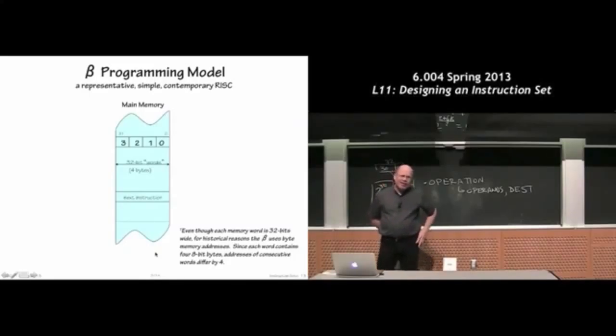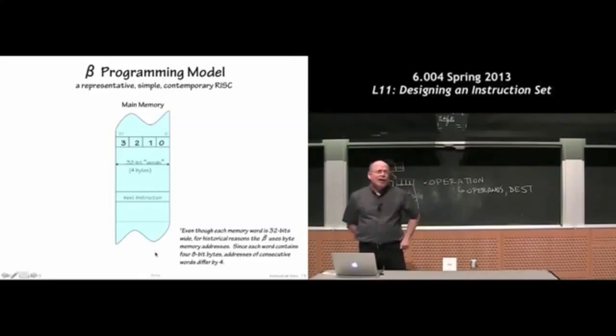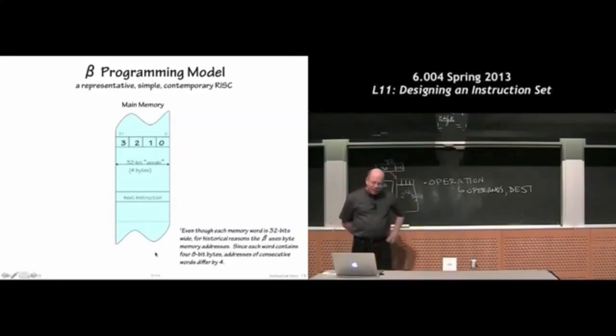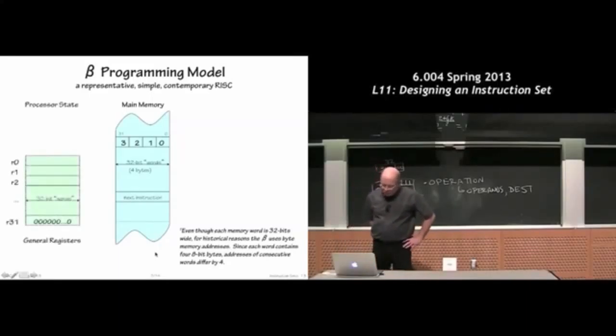And you can say, why are we doing this, Chris? This seems very complicated. Couldn't we just do a word address memory? Well, this is all sort of lost in the mist of history. We're trying hard to be compatible with machines that you're likely to see, which almost all support some level of byte addressing. So we've adopted byte addressing as our convention, but we're going to only use it to address words. So the bottom 2 bits of the address will always be 0.